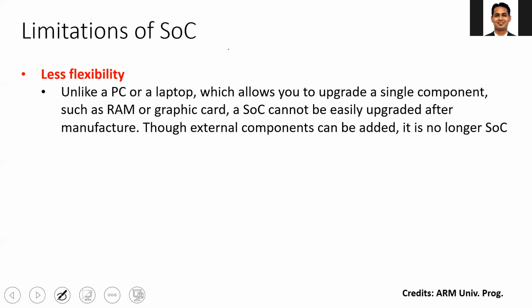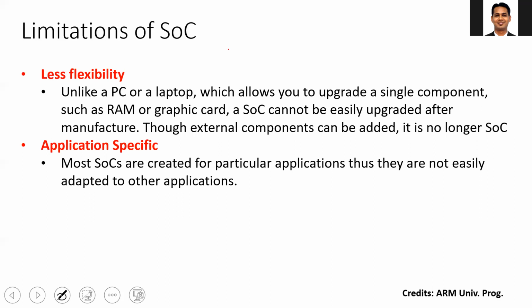Also, future upgradability is an issue, because these are application specific. Once you design a Bluetooth SoC, it will work as a Bluetooth SoC. Even if a new Bluetooth protocol comes in the future, it will not support it, and you need to replace it with a new device. Same case for a Wi-Fi SoC or any other application. For example, an FM device will support a certain frequency range, say 90 megahertz to 108 megahertz. If in the future the range changes to 90 to 110 megahertz, your current device will not support it. So it is application specific.